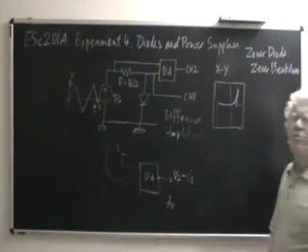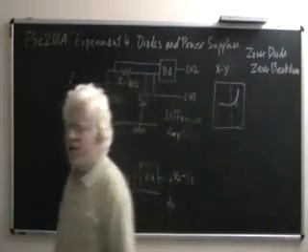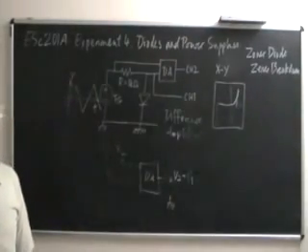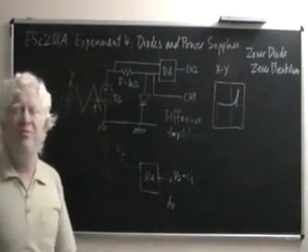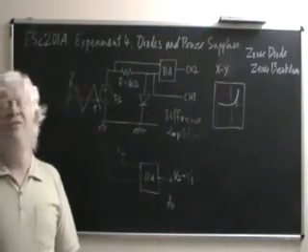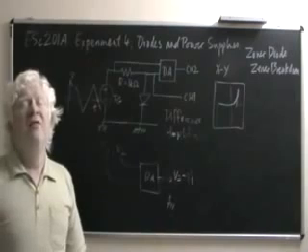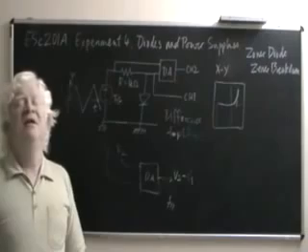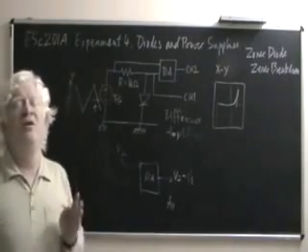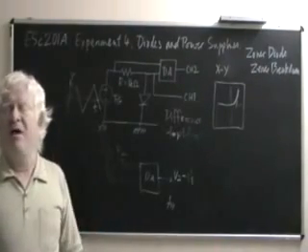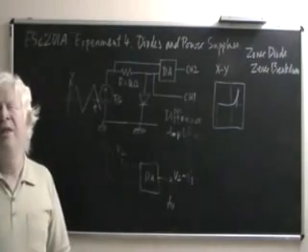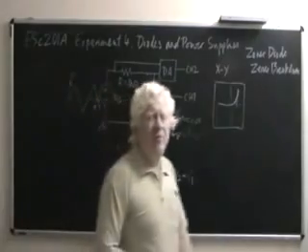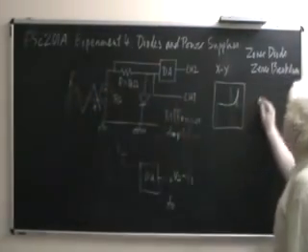The Zener breakdown is a repeatable phenomenon. You can Zener break down a reverse Zener diode any number of times. And one of the very nice features that a reverse broken down Zener diode possesses is a very, very constant voltage irrespective of current under breakdown conditions. In short, its incremental resistance under breakdown is very, very small.